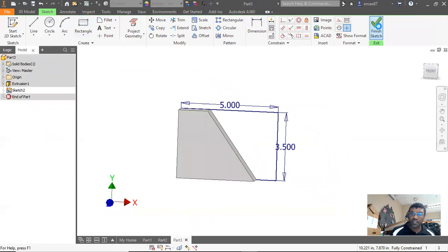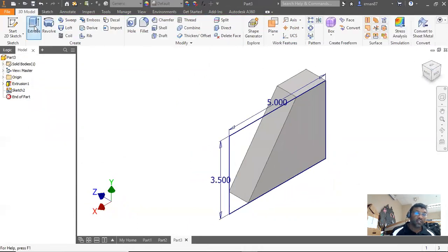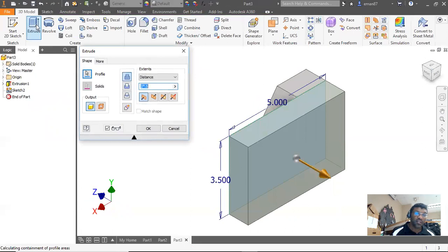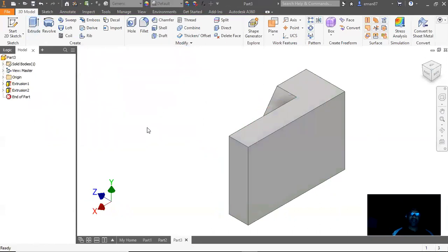So now I'm going to finish sketch like I did before. Rotate this around. I'm going to click on the extrude again. Notice since I have a good closed surface, it automatically starts to extrude for me. It's just waiting for me to input. I know that the extrusion is the same as the piece before, so nothing to change here. And I click OK.